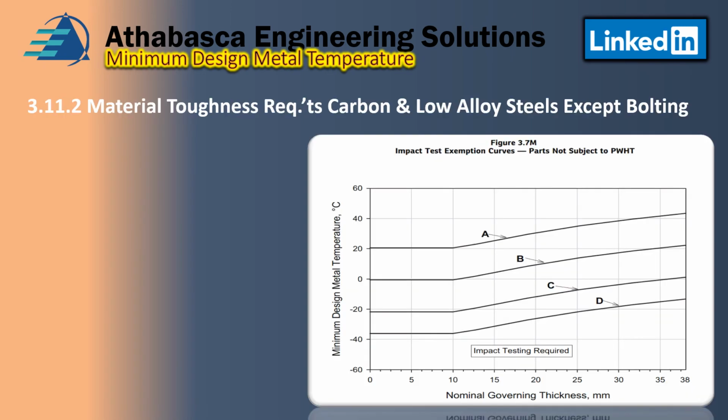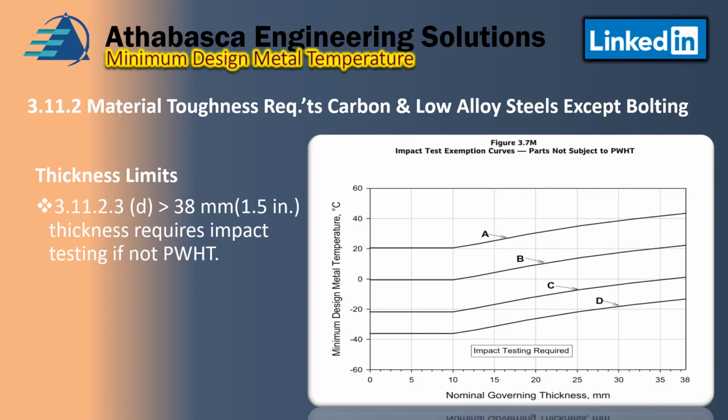3.11.2 in terms of the impact, the toughness and the thickness. You can see there's a statement buried within 3.11.2.3D: when you're greater than 1.5 inches thick, the thickness requires impact testing if you don't have post-weld heat treatment.